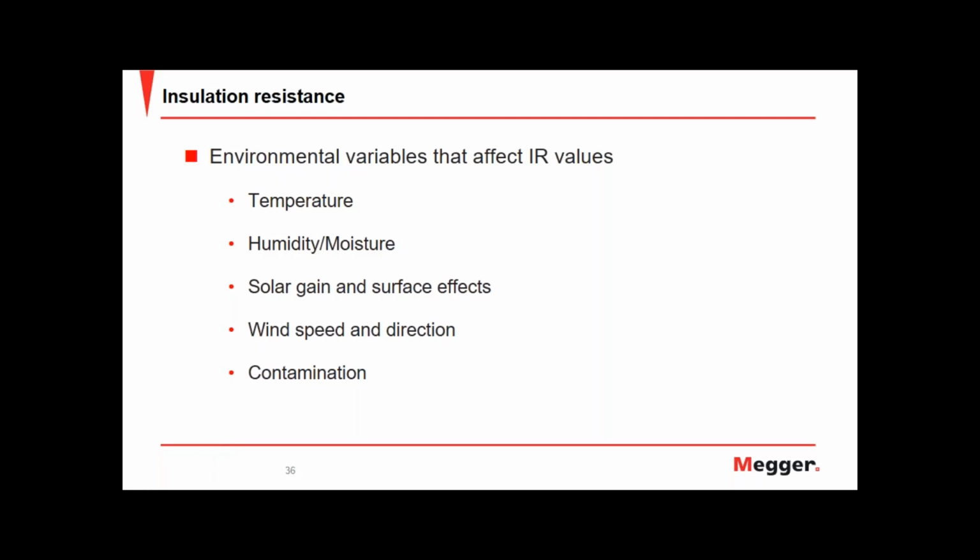Now, there's little that can be done to combat the effect of temperature on IR value, but it can actually be compensated for or corrected either in software or on board within the instrument using temperature correction.